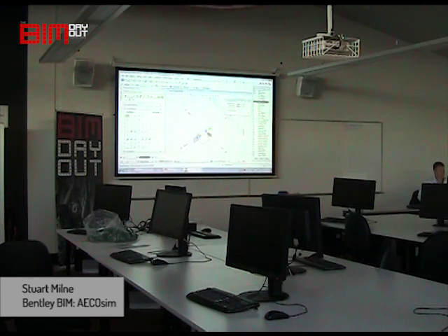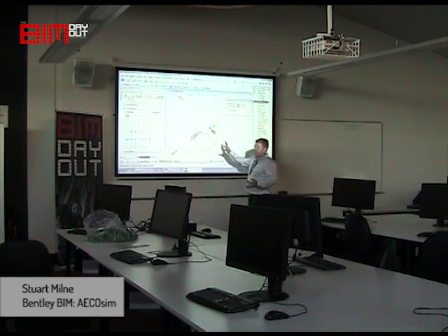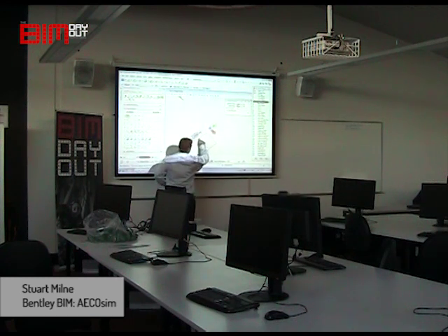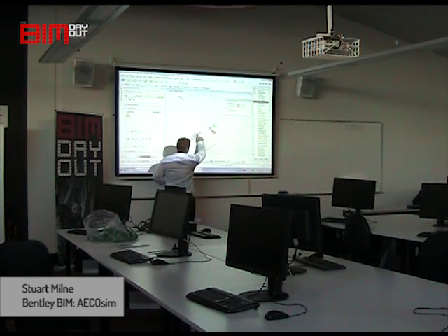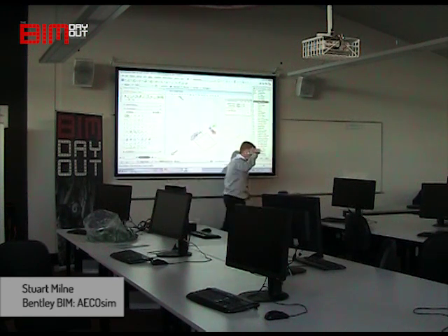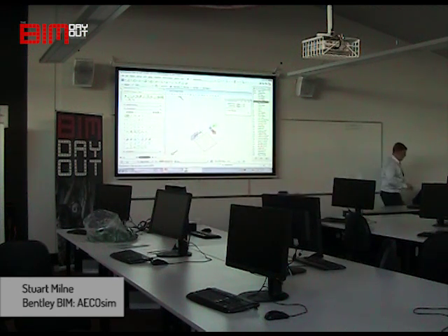Okay. You could type in the value 5,000 and then click, don't hit enter, just 5,000. Then click. Now, interestingly enough, we've already done this one before. We don't need to know the distance of that. If we just wanted to lock that into there and have it snap perpendicular to there, we just hit enter. Enter will lock the axis. And all we do is hit snap to the bottom point.